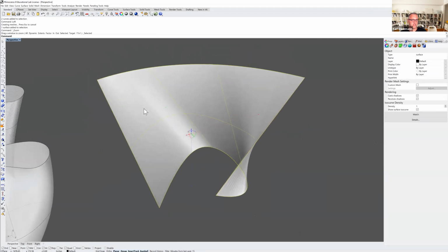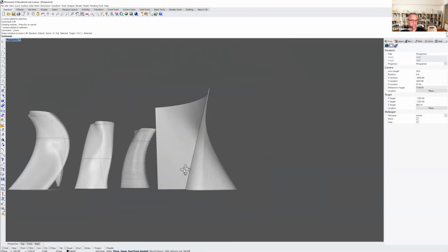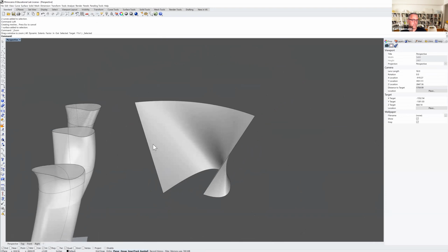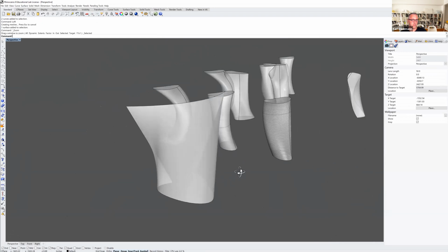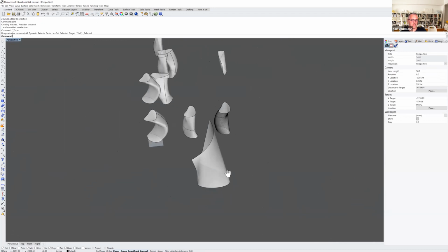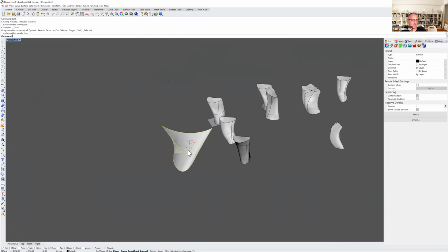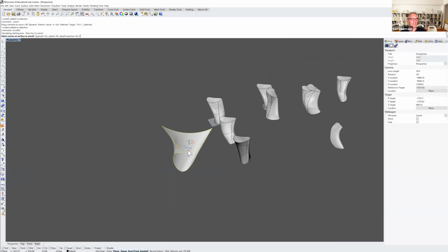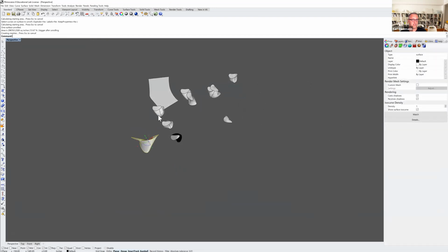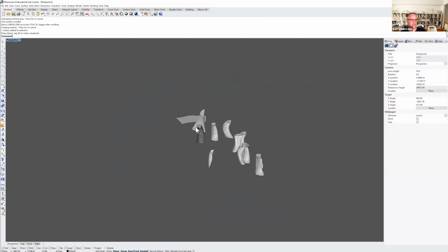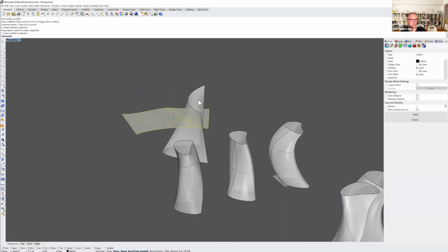And it also gives you a little bit of a sense that there's always a straight line drawn between these 2 curves, kind of divides them up. But what's also really nice about this is the ability to unroll these types of surfaces, which is another command. And if we're going to deal with fabrication or any of those things, unrolling is an important thing. And this then is that surface flattened. So between here and here.